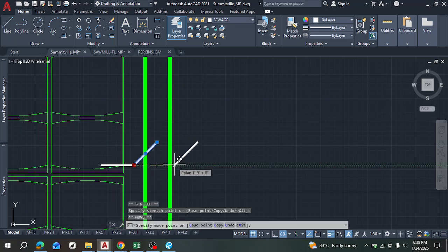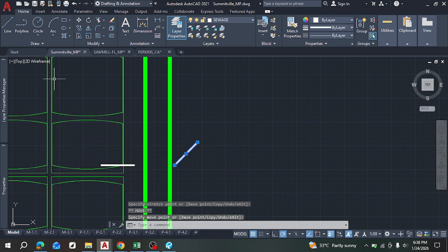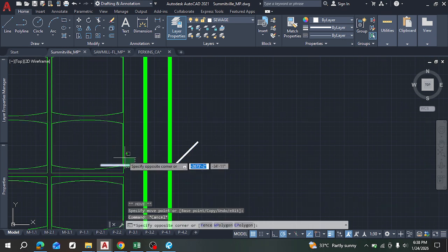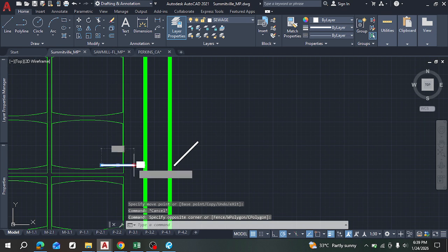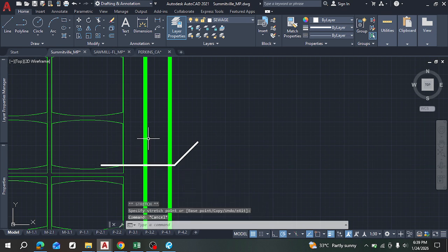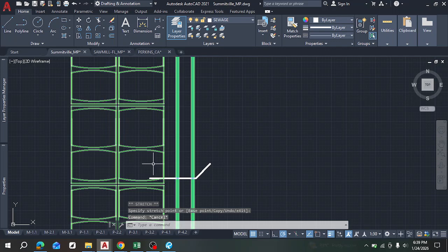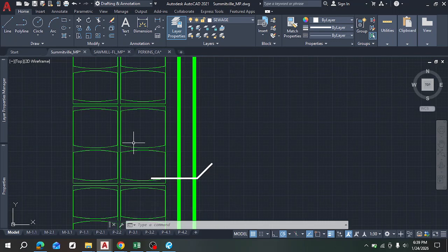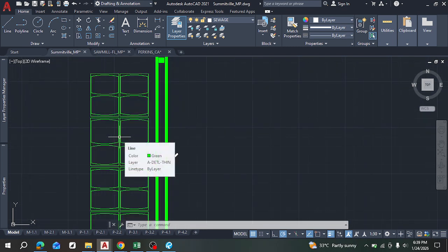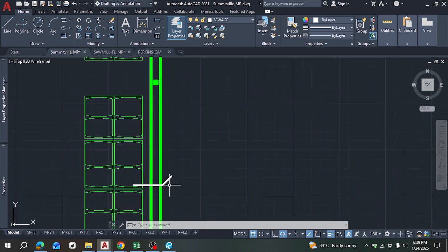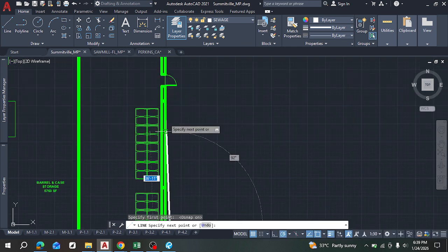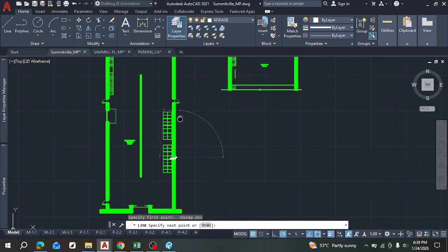This is just my own personal preference. The only thing I'm comfortable with passing in the wall is freshwater lines. But these drainage lines, unless I don't have a choice, I like to avoid. I would have passed it within this space, but that defeats the purpose of not wanting to pass it within an interior space where if there's a leakage, it's going to be a problem, as I'm taking it out entirely, right? The only problem we have to deal with here is it getting frozen, which is unlikely, right? So we go up, right?